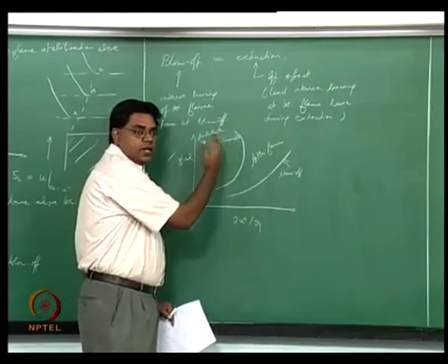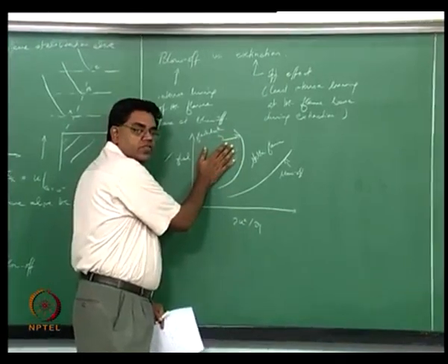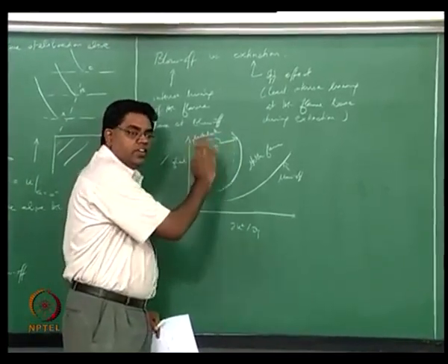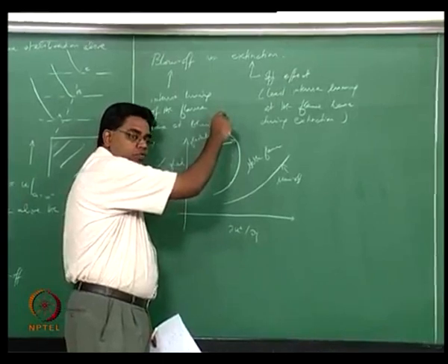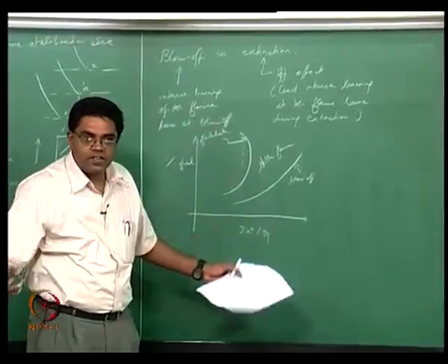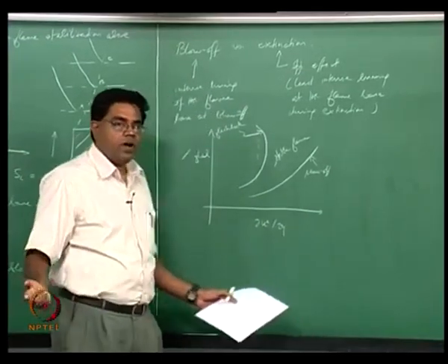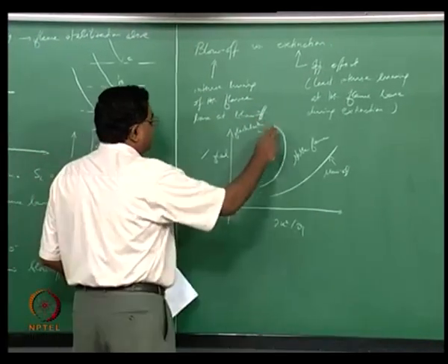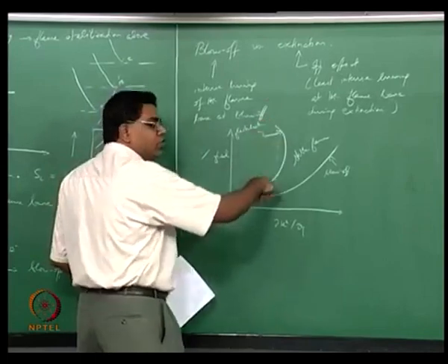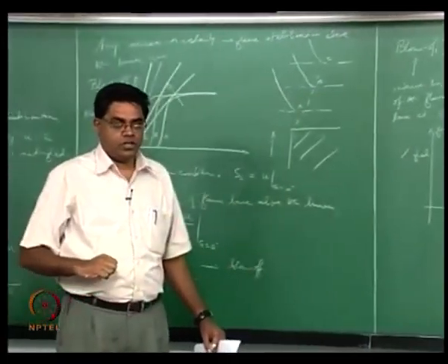And therefore you are going to flash back. So you now enter an unstable region. So you now can restabilize by either going in the direction of fuel rich or fuel lean, because on both sides the flame speed is going to come down, right. So it's possible for us to restabilize either by going the fuel rich direction or the fuel lean direction.